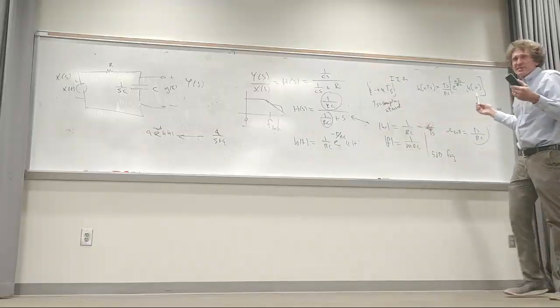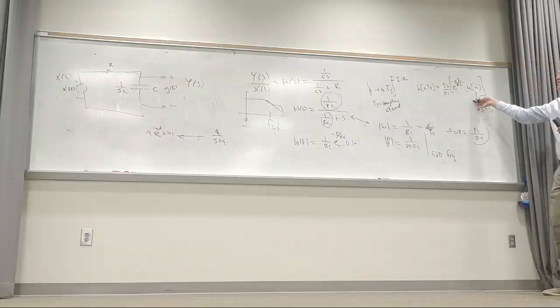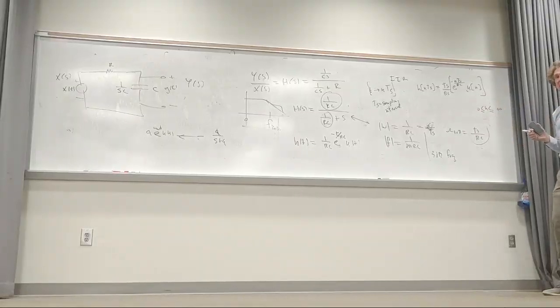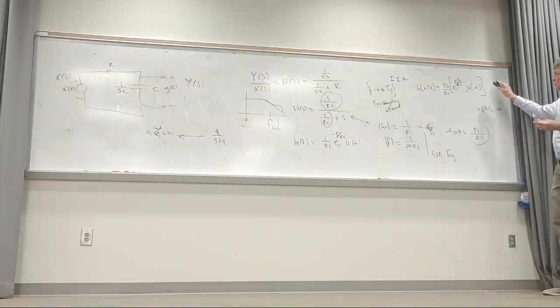We can get this, even 60 dB, but the problem is, for this thing to really work, you don't need 11 samples. You're going to need maybe 100 samples, and it still wouldn't be as good with the convolution as the one we did originally, where we took an ideal filter in the capital omega domain, got the H event for that, and then went ahead and multiplied it by a window and shifted it. That would do much better than this, is really what I'm getting at. And I don't expect you to know that much about this, but this is what he's talking about.